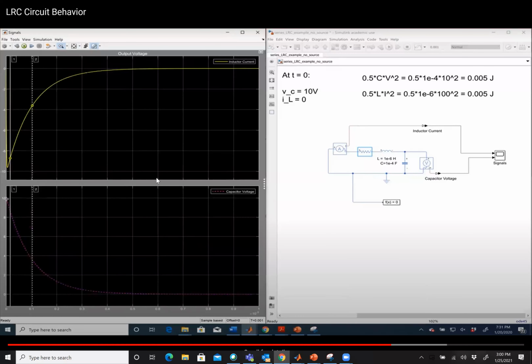All right, so eventually as I increase that resistance, if I look at this guy right here, I see it just drops below 0 and just levels off. This type of behavior, where I've lost all of that oscillation behavior, all of that sinusoidal behavior, I call this overdamped, okay? So essentially, when we get into second order systems, our responses are always exponential, but they can be complex exponential, all right? So Yawu will be talking to you about what that means in 2254.